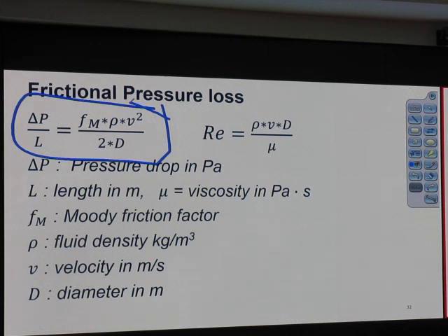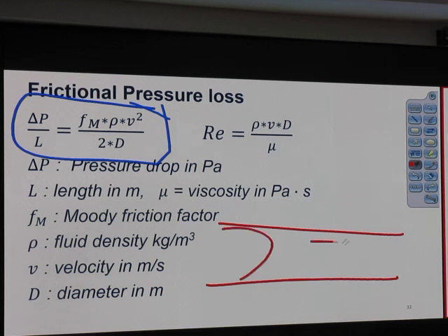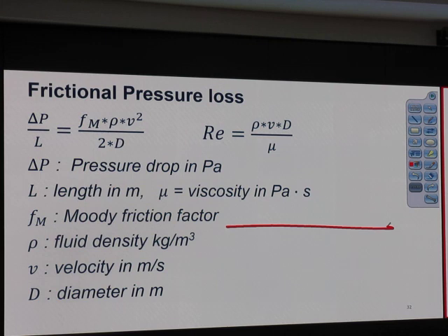So let's take a look at flow in a pipe. At the beginning, everything stops, no movement. When we turn on the pump, everything moves at the same time, right? So after a while, it arranges itself from stop to move, at the speed of sound, very quick. So that is transient during the startup. Speed of sound seems to be quick enough, right? So this is incompressible fluid. For the incompressible fluid, each molecule communicates at the speed of sound.